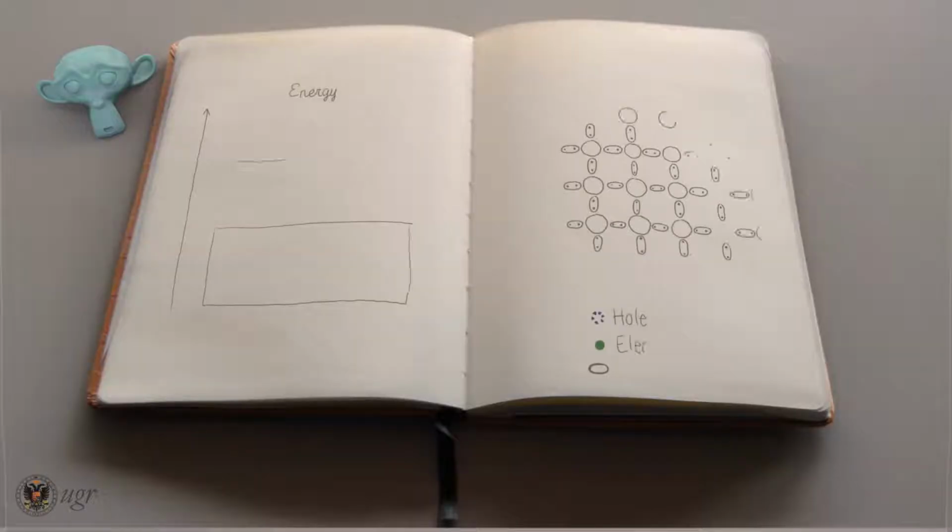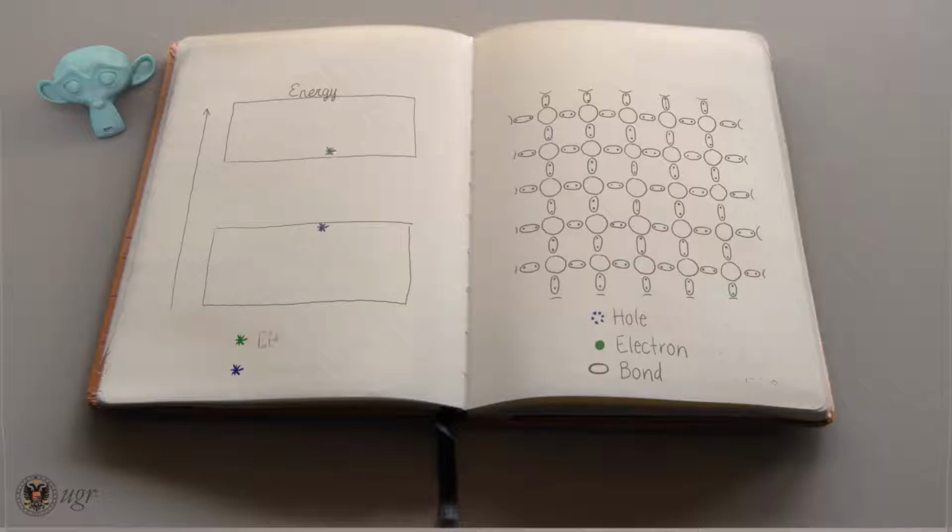In semiconductors, free electrons always have higher energies than those electrons forming the bonds between atoms. The range of energy values that free electrons have is called conduction band, and the energy values that bound electrons have is called valence band. Since the holes are the absence of electron in the atomic bonds, holes have energies corresponding to the valence band. There can be no electrons in the semiconductor with energies between both bands. Therefore, this interval is called band gap.